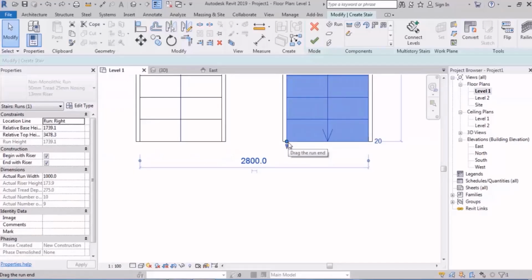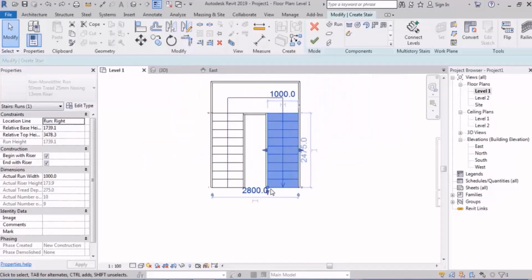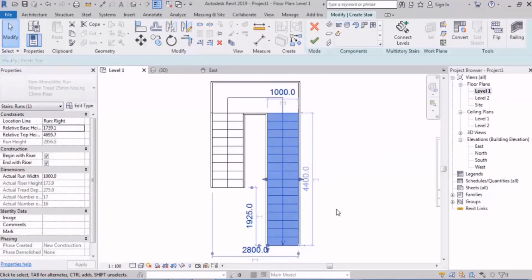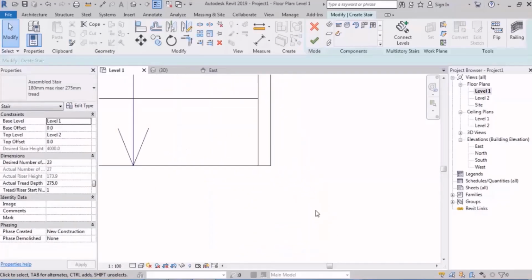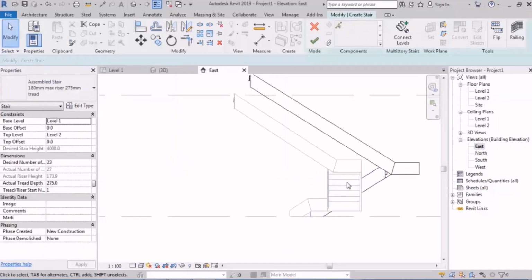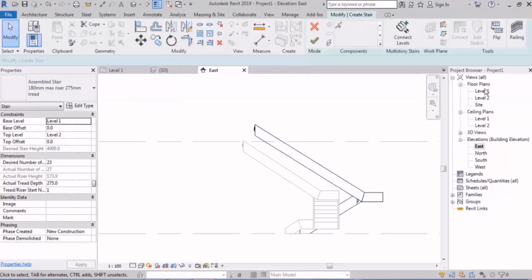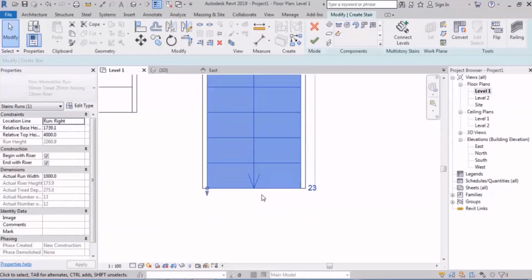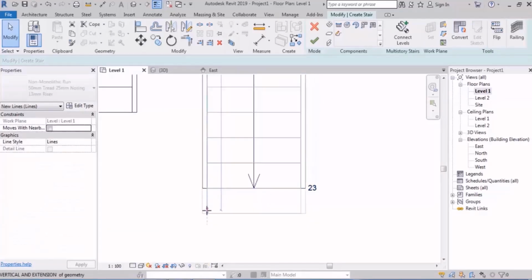Alright. Also remember that our edits don't always remain so nice. Actually, from now we start facing some errors. Now, for example, one of the things that we can do is that we delete this boundary, and instead of it, for example, I want to draw an arc. So I click on the arc from boundary, then I design the arc and click on finish. Pay attention. A message shows up. But what does it say? It says that the stairs run and landing cannot be joined.